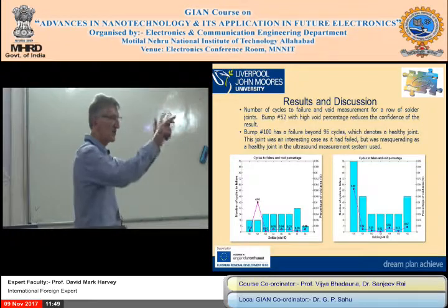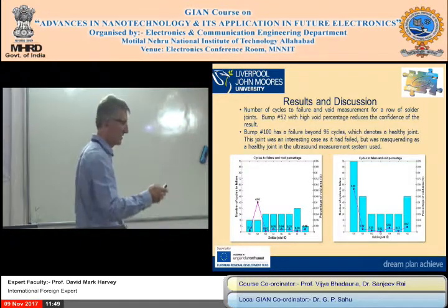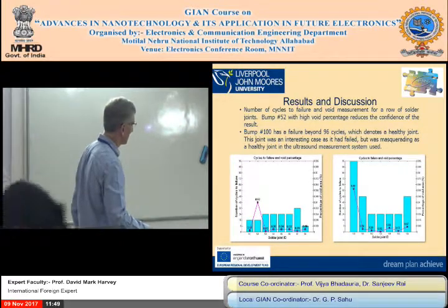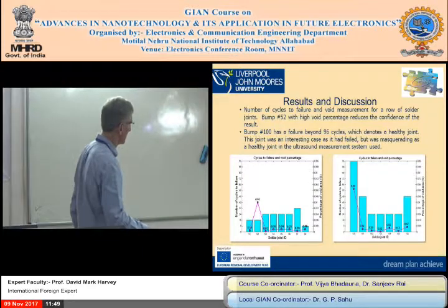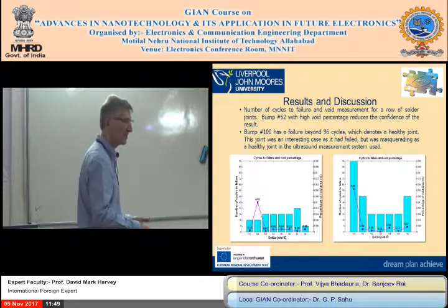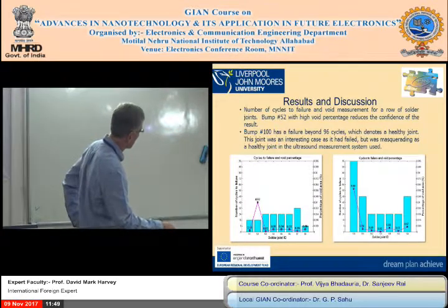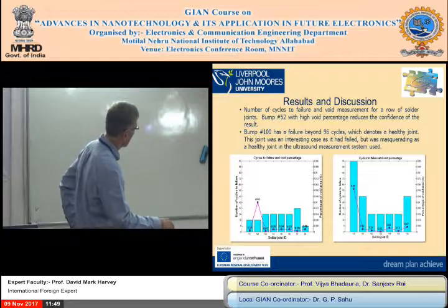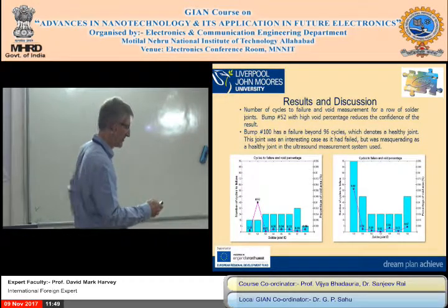And in fact, the distribution across the sides, both the short and the long sides, should be a Gaussian shape. But because this is such a short size compared to these, more or less all failed at the same time. You know, it's research, you find out new things. This one here, you can see, it's almost got a distribution type shape. This one here, because these joints haven't failed, would have probably continued on. So it's bottomed out on the top.